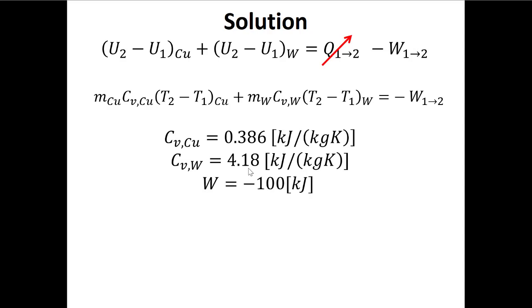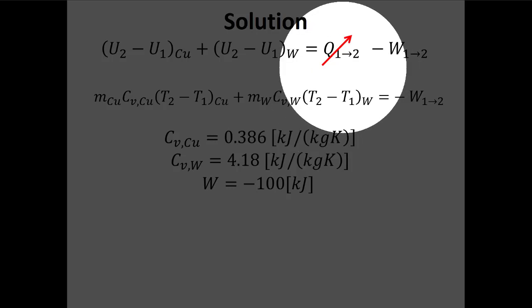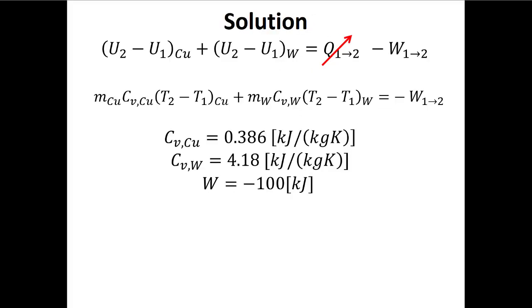Now, the part here that could be seen as being tricky: what do I do with that energy that comes from the resistor? My first inclination may have been to call it heat. But then I also assumed that the heat into the system was zero. So instead, I'm going to call this work, because I could use that electrical energy, presumably, to generate a force,